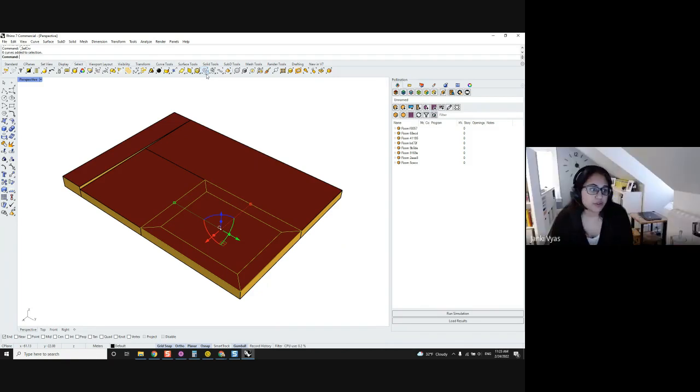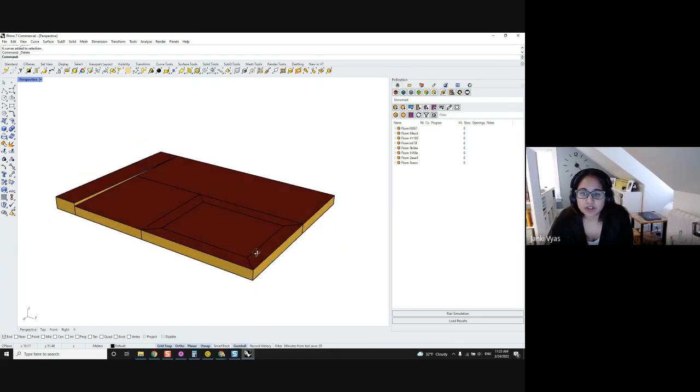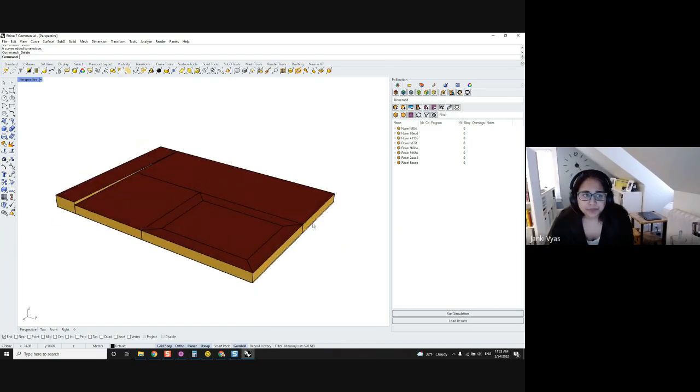Yeah, it allows you to do more than just splitting the room into 2 rectangles or 2 squares. You can get pretty intricate with how you're carving sections or spaces out of your rooms. There are some native Rhino commands that are really helpful, like select all curves, so that you can delete all the curves you had, just to keep a clean model.